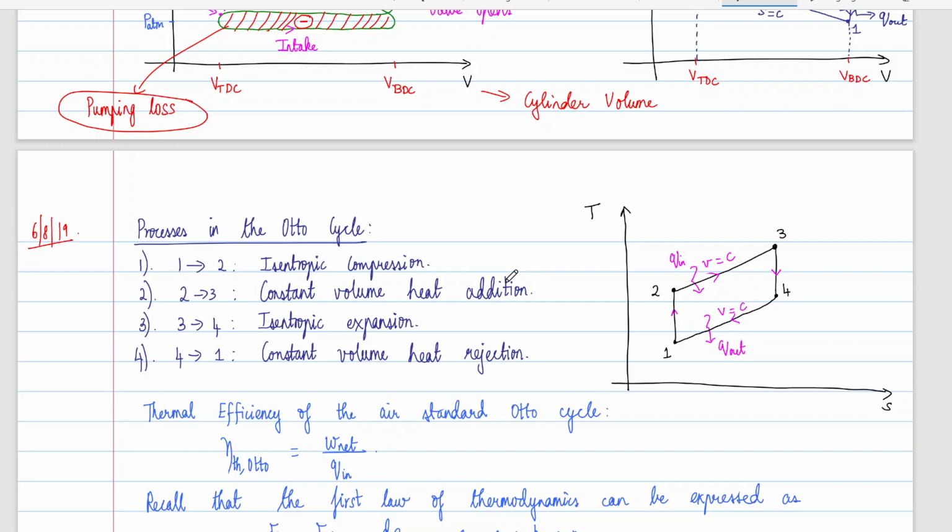So it will be spring loaded, and when the engine is rotating, the clutch will rotate with it. Once you reach a certain level of RPM, there are some pads which are held together by springs. As you increase the rotation, the centrifugal force acting on those pads will act against those springs,